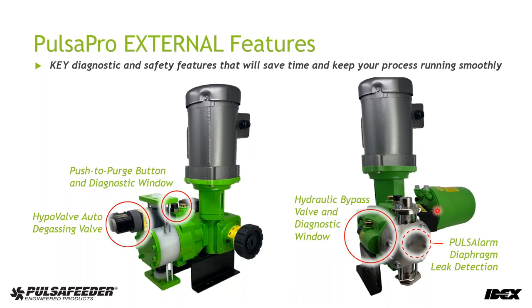This is a 3-component check valve assembly that's supported and installed with a 4-bolt tie bar system that's very rigid. You can see here, this is a stroke length adjustment mechanism. This is a manual version of that. And then over here on the right is what we refer to as the XAE controller, which is an automatic electric stroke controller with a ton of features on it. We have a whole webinar based on that all by itself.